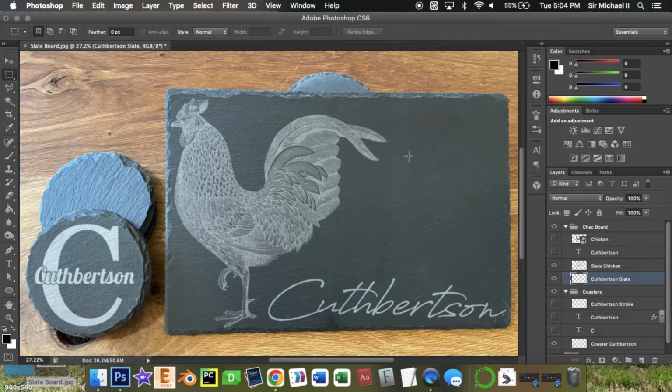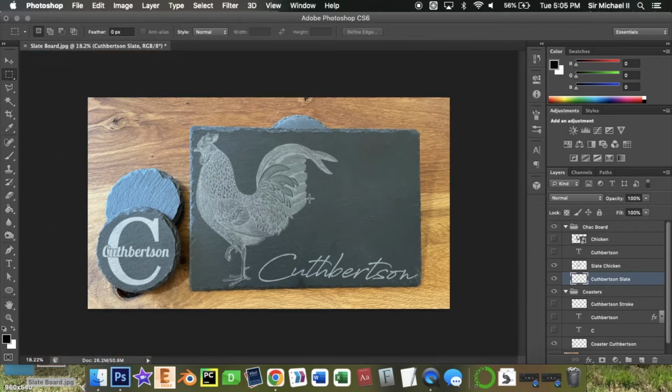And that's it. Now, before I started faking my listing photos, I engraved a lot of different things, so I had good reference images. Reference images are key here. Whatever reference images you have, adjust your brightness and contrast to make it look like those. This is just how my laser engraves on this slate. I've worked the image to match that. Whatever your laser does on your material, you need to change it as such. But other than that, it's that simple.